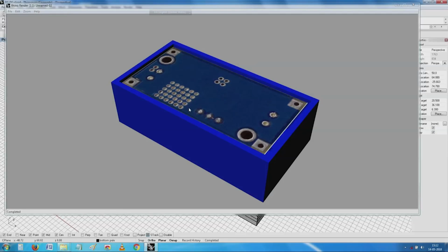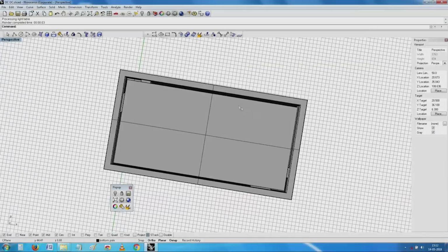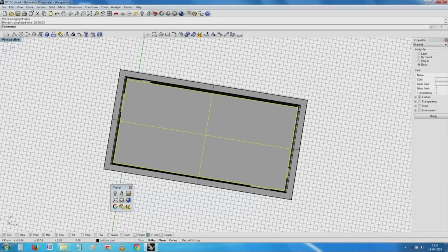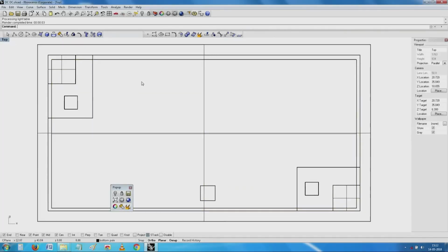So, for me to do that, I need to create the heat sink plate on top of it, and to make use of the extra area available here, I am going to make a simple rectangular plate all along, and then I am going to have these 2 holes, and then we just need to clamp it. Except that you will notice we still have these 4 corners which are likely to create a problem for us. So, when I try to create a heat sink for this, I will continue to use this, there is no problem about it, it is the same plane. You have seen this, same plane, I can try to make a heat sink out of it.